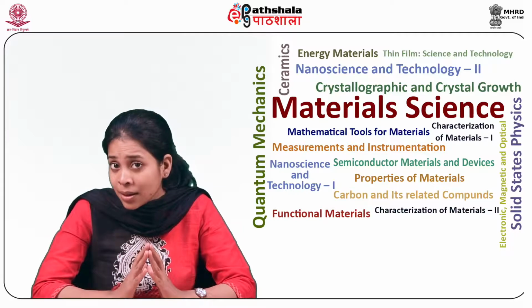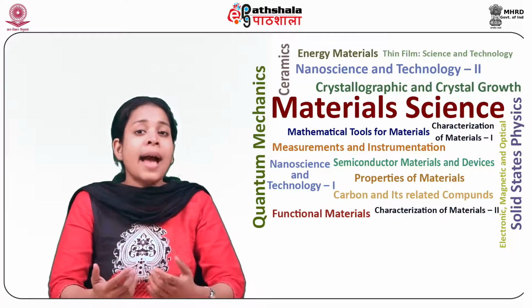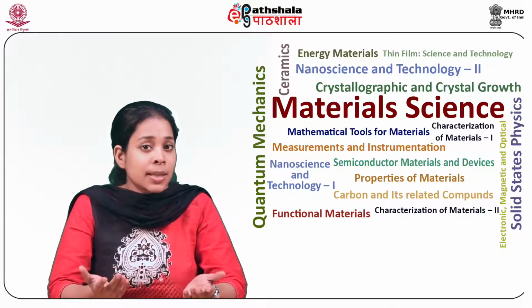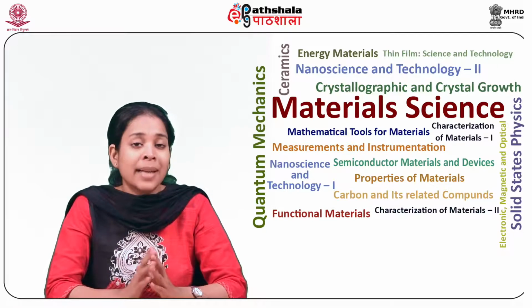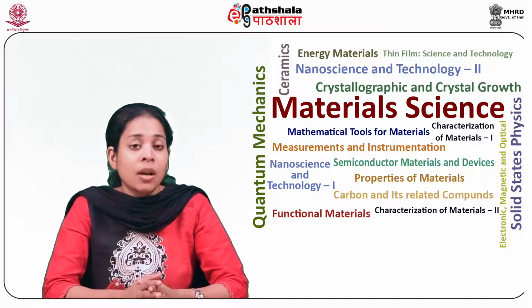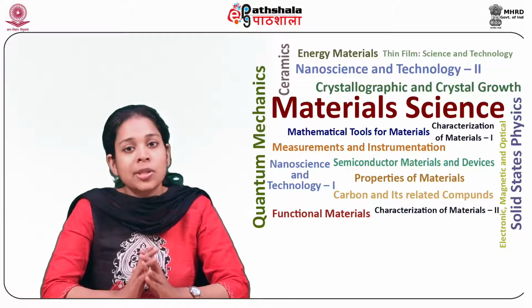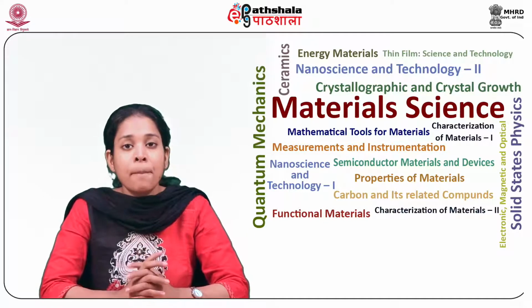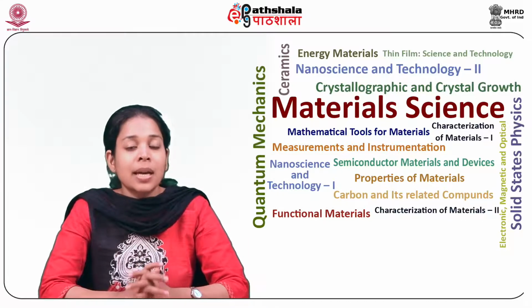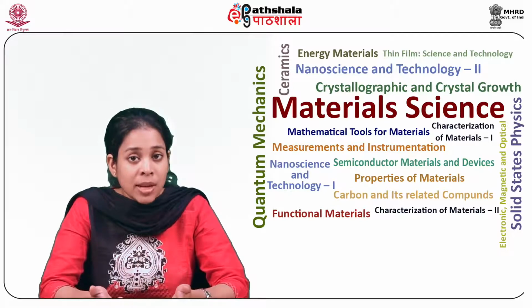As discussed earlier, the TEM mode is transverse electric and magnetic mode which exists in the structures having two conductors surrounded by the dielectric medium. So the quasi-TEM mode is very much similar to the already discussed TEM mode, but it is present in microstrip resonators and coplanar waveguide resonators.